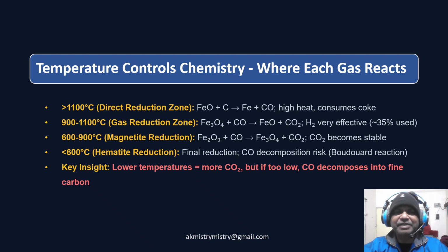The simple message is lower temperature generally produces more carbon dioxide, but if you cool too much, you risk carbon deposition, and carbon deposition is also like a hidden bomb. Many times it gets into the perforation of a material or refractory, and when there is an expansion it just bursts.